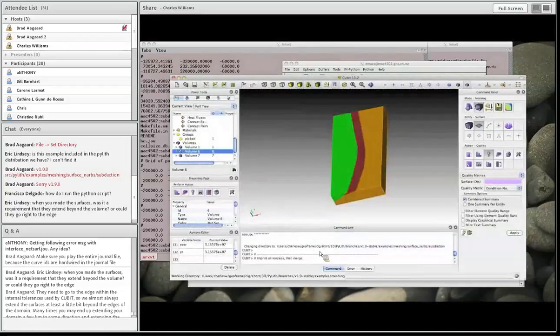For this particular problem, we haven't actually done anything complicated with our discretization size. We're going to mesh it using tetrahedral cells, and we're going to just use constant mesh size. So it's actually pretty straightforward. And I can't even remember. We do define blocks and node sets, but for this problem,